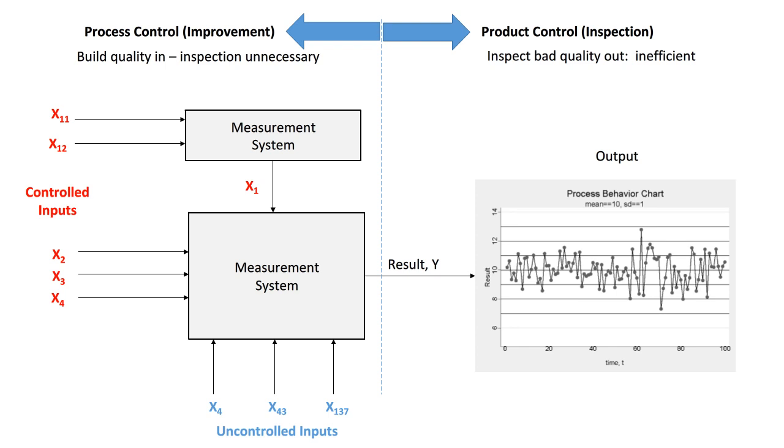This brings up a useful point regarding terminology. This is the difference between process control and product control. Product control involves inspecting the final result and determining whether it is acceptable. Process control involves looking upstream, identifying and controlling assignable causes. In product control, we inspect quality in. We examine each run and throw out the faulty ones. By doing this, we retain good results and achieve high quality.